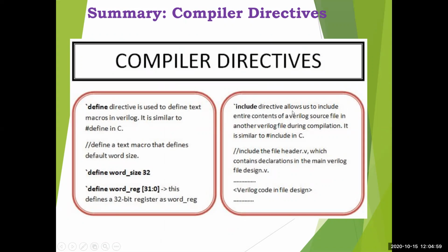And then the `include directive allows us to include the entire contents of a Verilog source file in another Verilog source file during compilation. It is similar to #include in the C program. So we have examples. So this is about the very first basic concepts we are learning in the Verilog language.